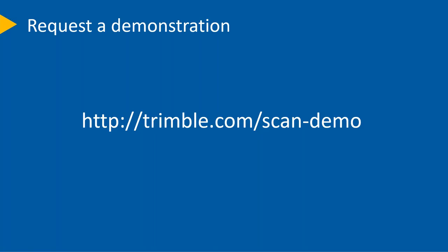And you don't have to scan the whole thing with the SX10. You can do a station setup, so you're already geo-referenced in the coordinate system that you want to work in, and then just scan the areas that you need. For example, maybe you need to capture the top of pipe for a drainage pipe, and maybe one end of the pipe somebody has run over, so it's all crumpled up.